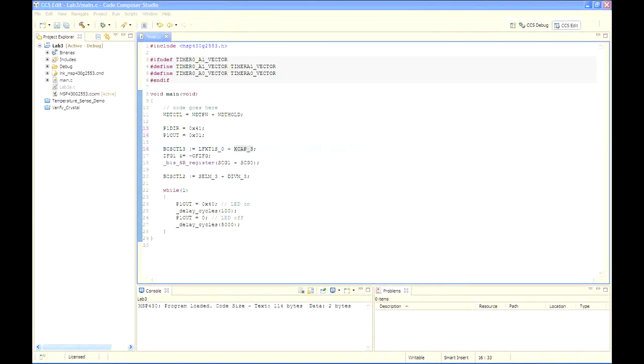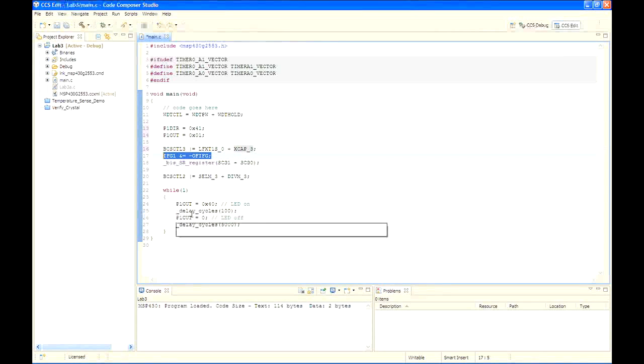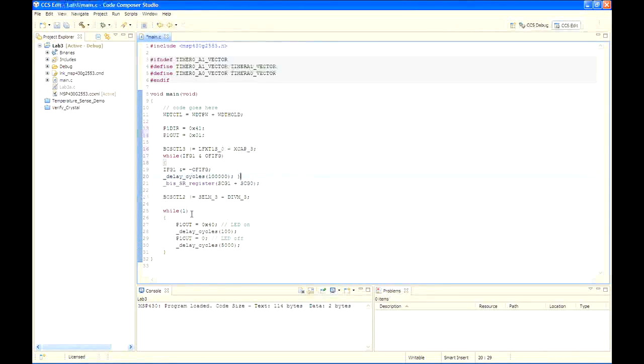In step 18, in the previous code, we cleared the oscillator fault flag and went on with our business, since the clock system is going to default to the VLO anyway. Now we want to make sure that the flag stays clear, meaning that the crystal is up and running. This requires a little loop with a test. So we're going to modify the code that simply cleared the flag, and write a little piece of code to test the flag and make sure it's cleared.